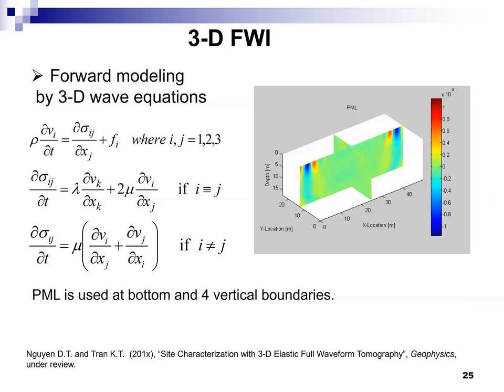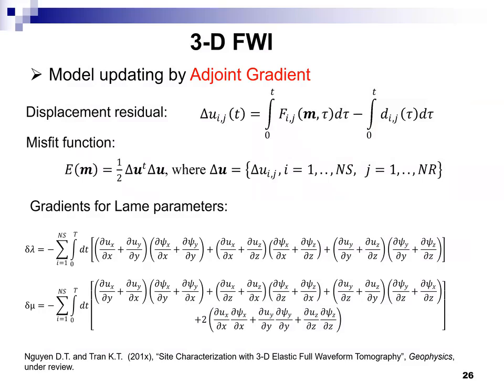Right? Did you use FDM in the 2D result as well? Yeah. Finite difference, because we don't have to solve the inverse matrix of the stiffness matrix like the finite element method. So it's faster, basically. But FDM cannot model the curve of the domain. Yeah, we are working on that. We use a triangular element for the finite difference method right now, so we can model any shape.